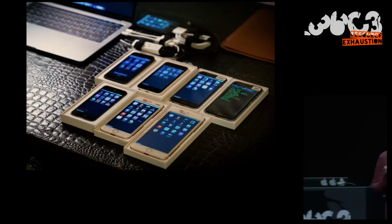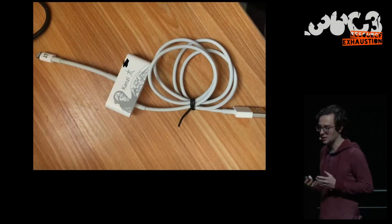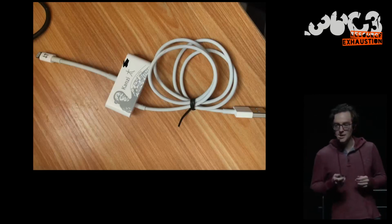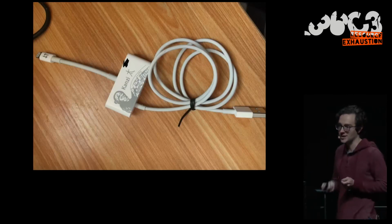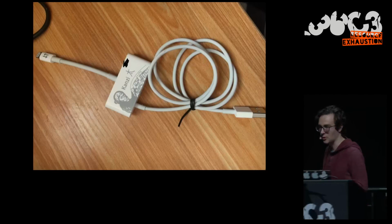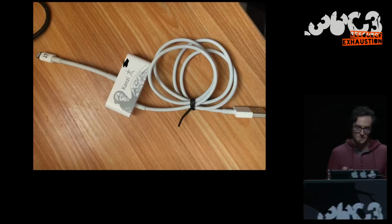Now, in order to connect to these special types of iPhones' debug capabilities, you need a really special type of cable, usually called a probe. Here's an example of what's called a Kanzi cable. It has a special lightning connector on one end, which has a special accessory ID burned into it, which allows it to communicate with the debug hardware on the phone. It has a controller, the chunky part in the middle, which is able to talk the debugging protocol. And it has a USB port on the other end, which you can connect to a laptop.